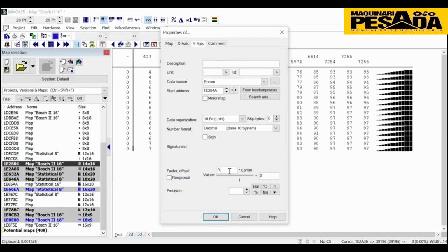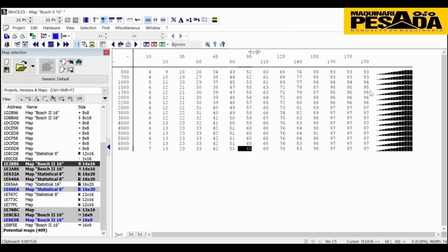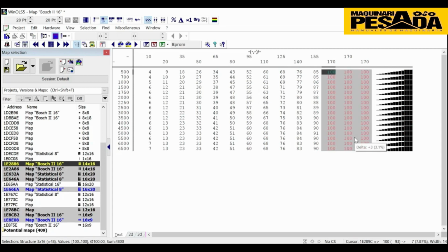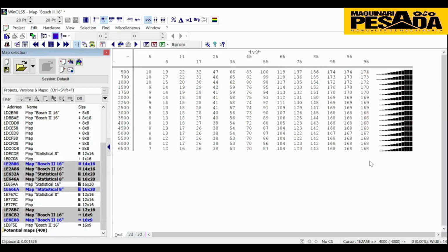and here you can see something amazing that I'm going to explain to you. Look, this is optimal engine torque. You can make these 3 columns 100. When you make it 100, it means that you increase to 100% of torque, and the ECU can generate more than 100, more than the previous one that was around 97. Okay, 100%. Then you need to go here to load and set these values to 100.